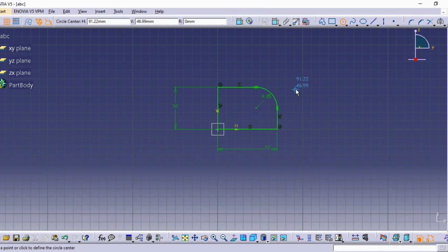That is opposite of pad. Okay, so you're in pad, you're adding material. You have removing material option as well. So you can select that and do the process, or else you can give it here directly. It will save you one step. So I'll create the circle here. I'll press tab and give the radius as 10.